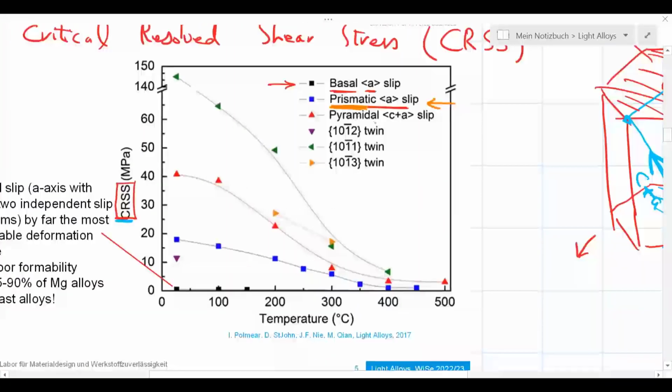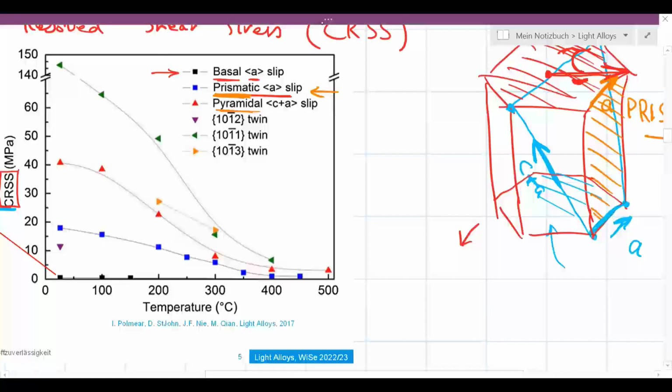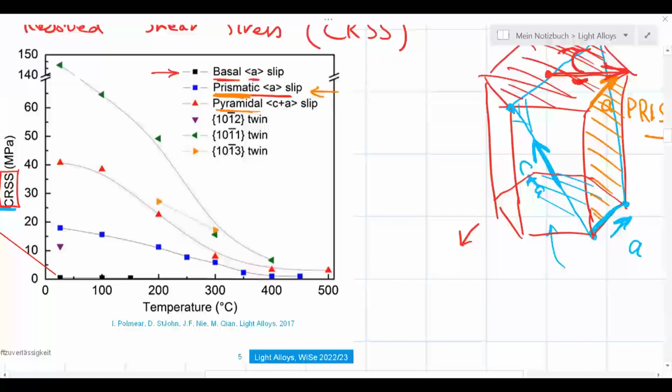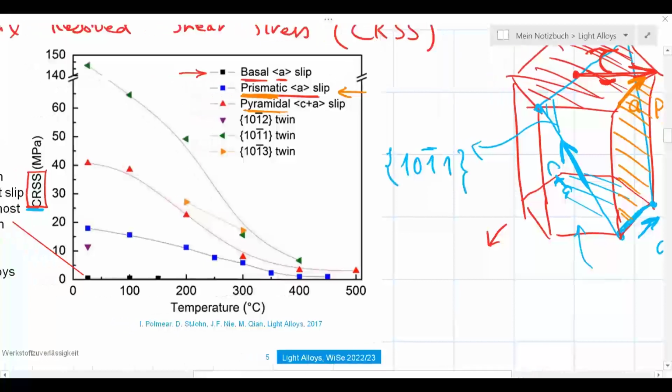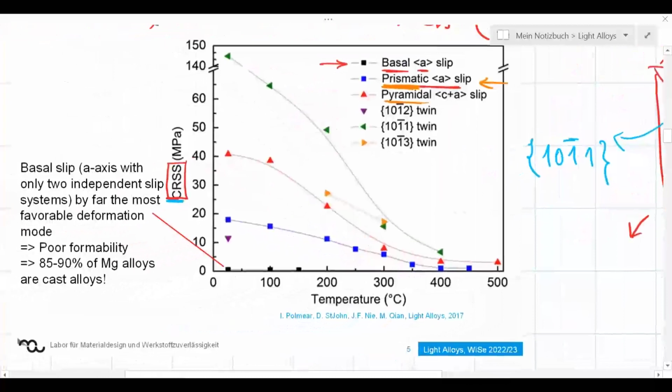And for pyramidal type of slip, I put blue here in my schematic for one of those pyramidal planes. What kind of Miller index do we expect here for the blue one? Let us see. So I think this is 1, 0. It is cutting c at 1, so we get 1 here. Sorry, we get 1 at the end, and here we get -1. So the one I drew there should have this sort of Miller index, right? That is a Miller index for this type of plane, pyramidal plane. Good. They could get activated, and we see values for different types of glide systems.